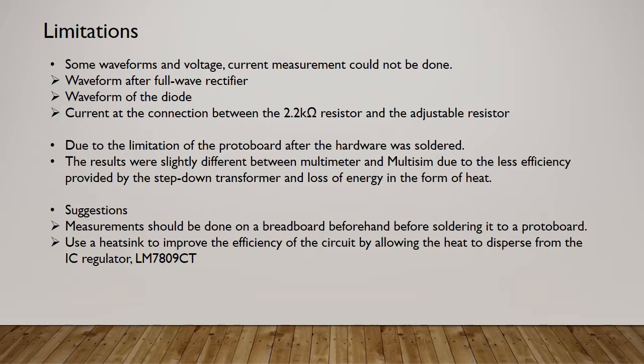This is because of the limitation of the protoboard after the hardware was soldered. Measurements should be done on the breadboard beforehand before soldering on the protoboard. And a heatsink should be used to improve the efficiency of the circuit by allowing the heat to disperse from the IC regulator.